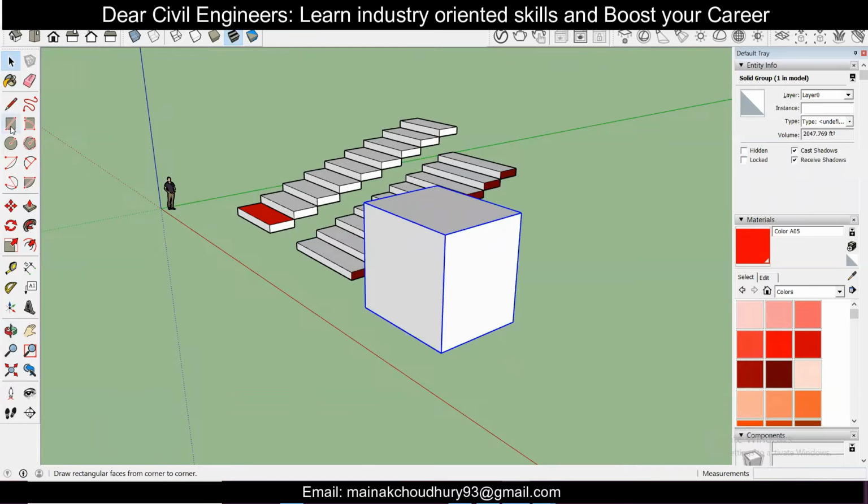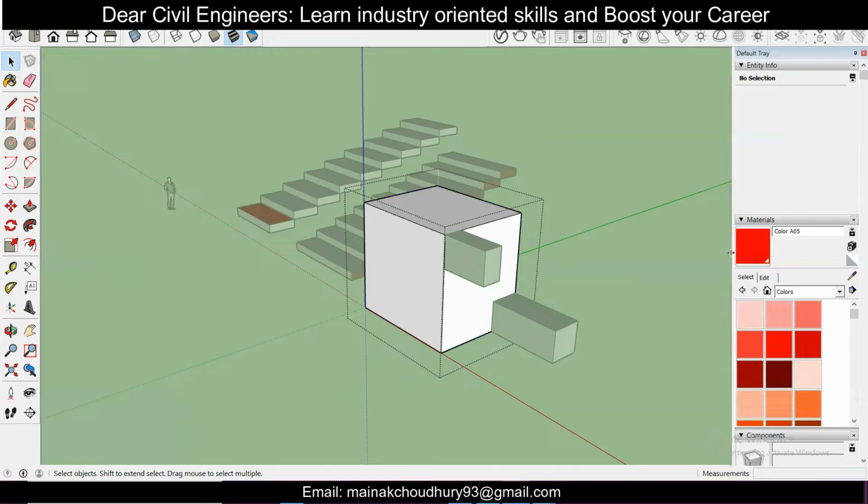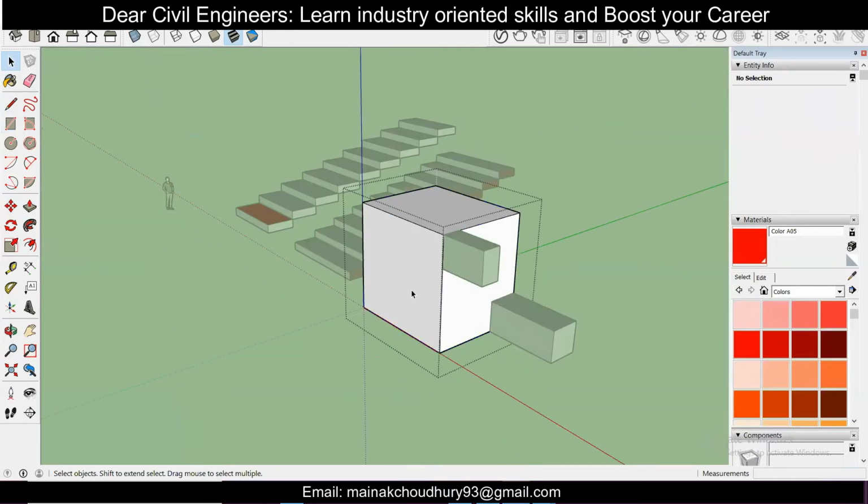And suppose I want to make any other surface out of it. Suppose I want to make a surface like this and a surface like this, and I can make another surface here like this. Suppose I want to use the Push/Pull tool here again to give a particular depth to these surfaces. Now suppose using the Select tool, I can triple click, and I can make any changes here.